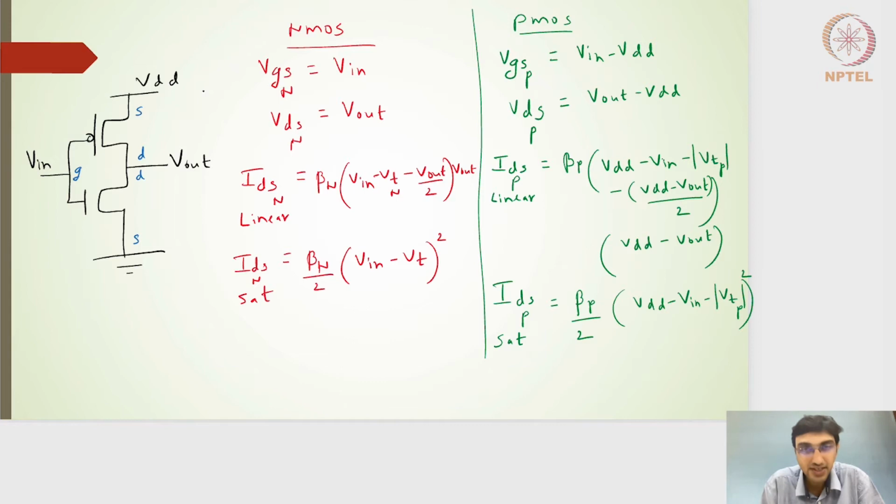So rail in the sense, in most of our digital circuit designs, we will be calling the rails nothing but a power supply. We call it the rails. The reason being, the rail is defined for the transistor when it actually goes into the layout. Right? When we fabricate, we have a metal line which is powered by the VDD rail, which is powered by one particular power supply, and another one, the ground metal line, which is connected to the ground power supply. And that is how the term rail has been defined for the digital circuits.